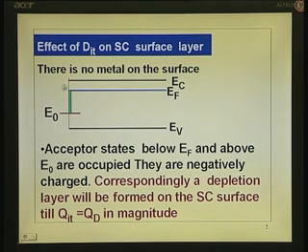which illustrates the conduction band, valence band, Fermi level, that is N type material, and we have the DIT distributed all through the surface here. I just put this E naught here. Whatever levels are there above E naught, they are all acceptors.